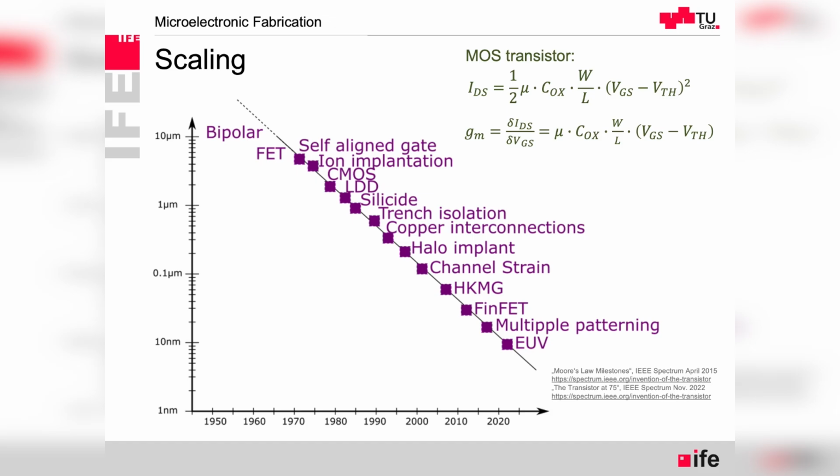Then we can see here the copper interconnections. That's one more thing that I'm still going to highlight. In scaling, what we have seen is that the power density decreases, the transistor scales down, the metallization also is getting more narrow, but the power consumption is still very high, and we don't want to have high power dissipation in the wires. So one thing that could be done is getting a metal material which has better conductivity.